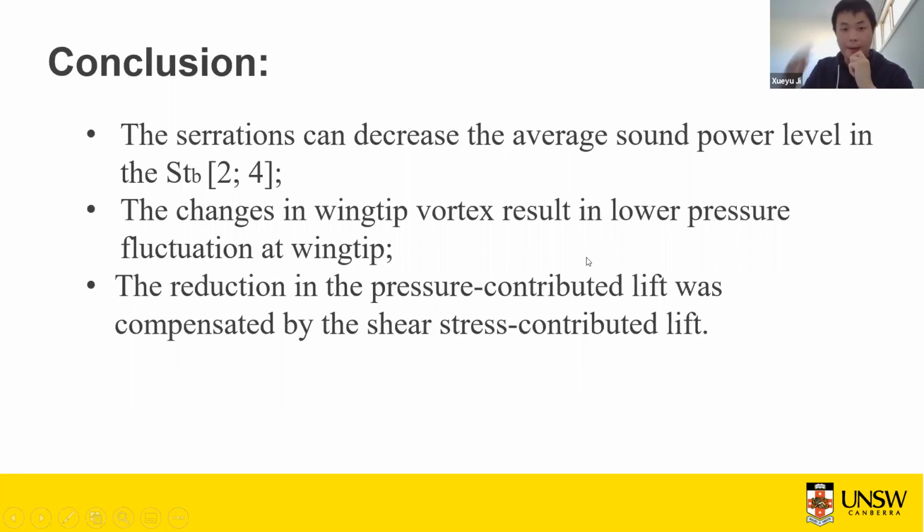The conclusion is that the serration can decrease the average sound power level in STB, and the change in wingtip vortex results in lower pressure fluctuation at the wingtip. The reduction of the pressure-contributed lift was compensated by the shear stress-contributed lift. And this is the conclusion.